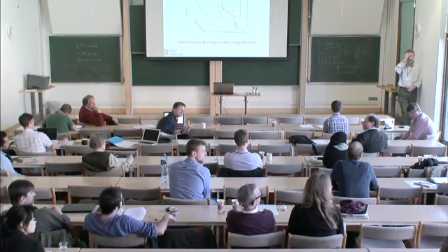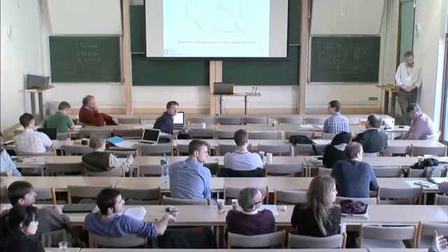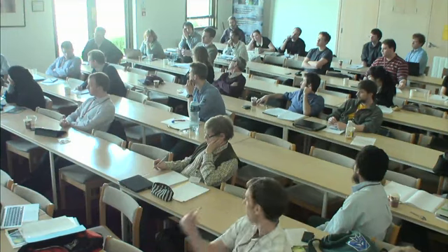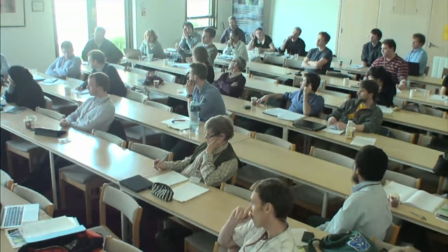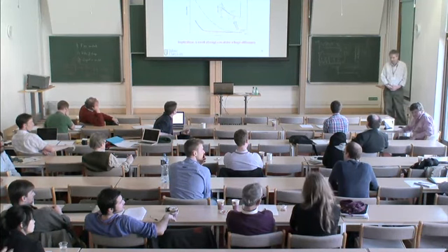Yeah, I was thinking that's true if there's a transmission constraint, but if there's basically just not enough load to absorb the wind energy, actually it could be good to have the storage quite close to the load, because some of the wind energy that would just be wasted otherwise is absorbed in the losses. So I don't know how much that actually turns out to be, but this is something.